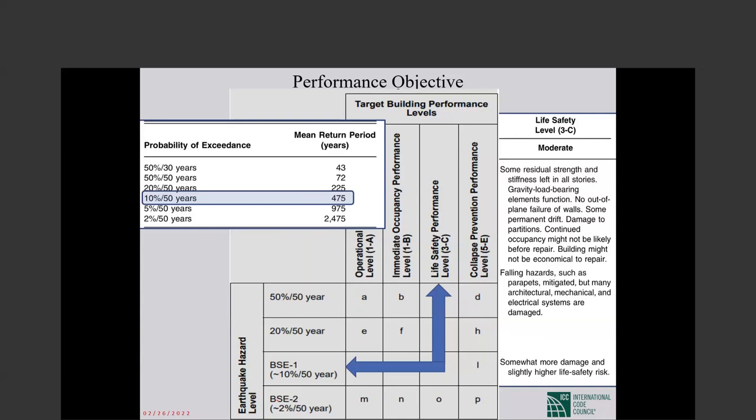But in the evaluation, our methodology for systematic evaluation should be such that for every earthquake hazard level that they want and every performance level that they want, we should be able to check it. The earthquake hazard level in the linear analysis method will be the base shear.